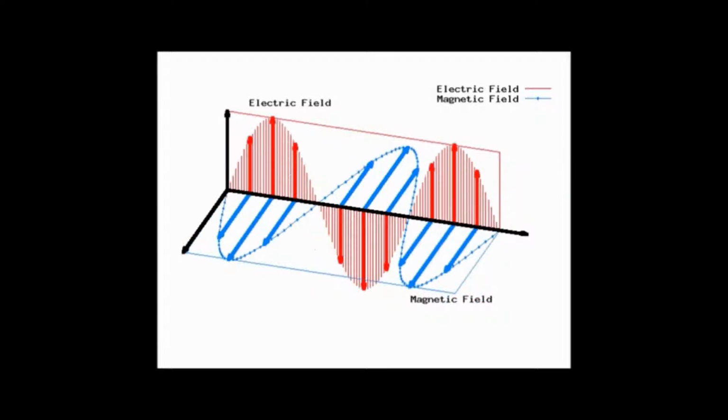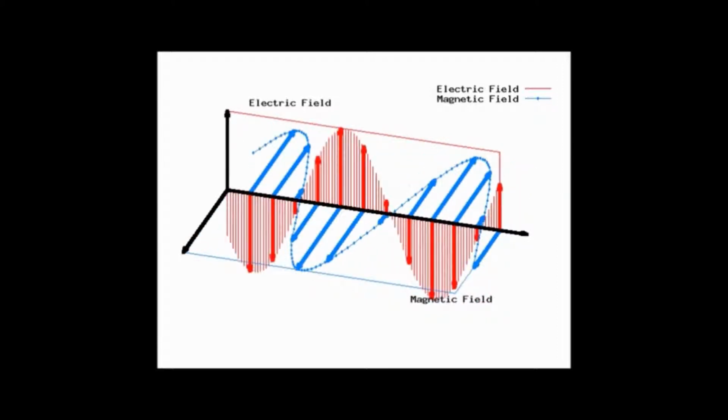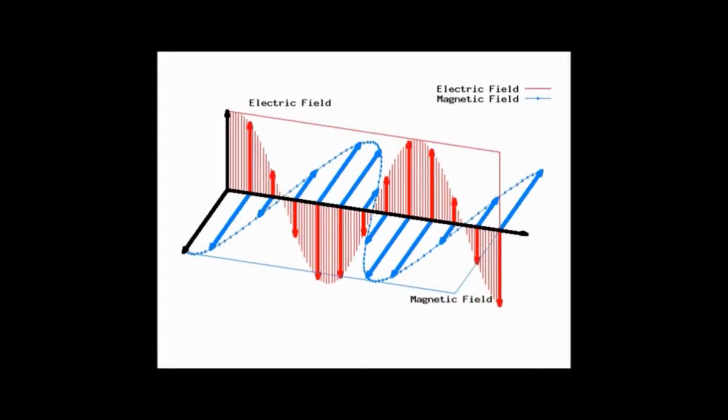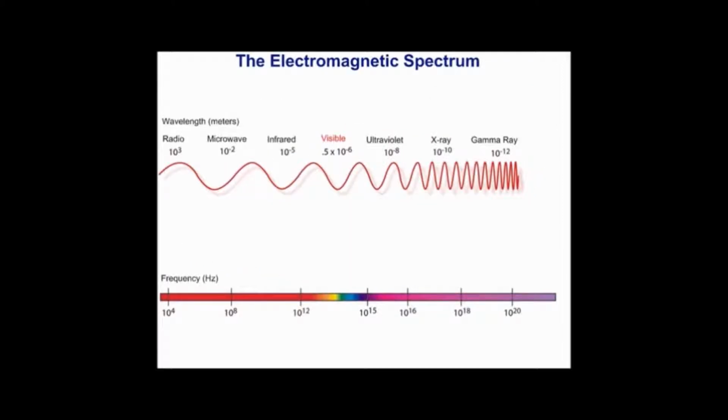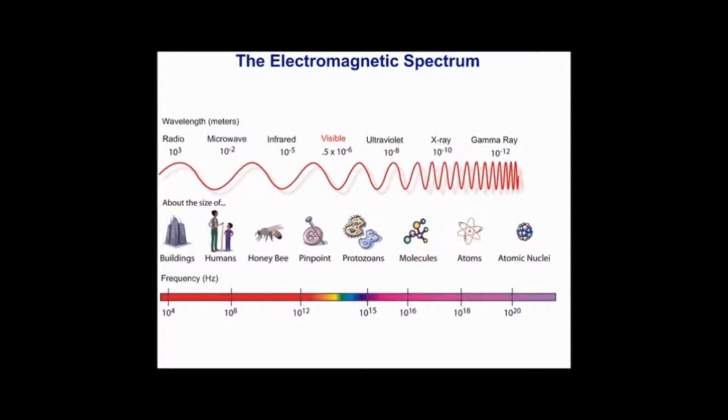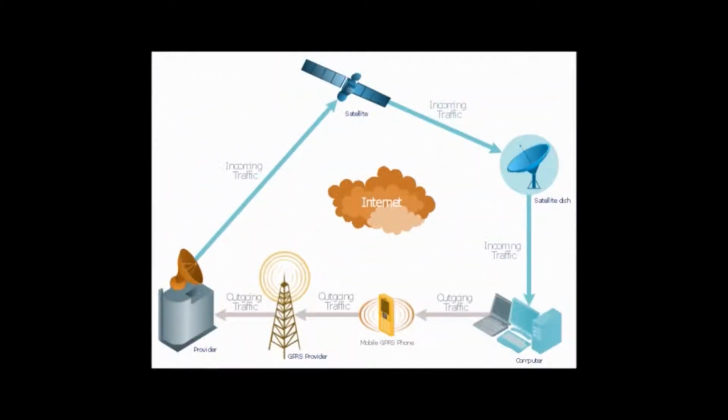The frequency of electromagnetic waves is measured in hertz, which is 1 cycle per second. In the spectrum of EM radiation, conventionally, electromagnetic waves that range from 30 kHz to 300 GHz are called radio frequency, and those over 300 MHz are specifically called microwave. The corresponding wavelengths range from 1 mm to 1,000 km. Radio frequency is used in radio transmission, TV, mobile communications, and data navigation as in GPS or satellites.